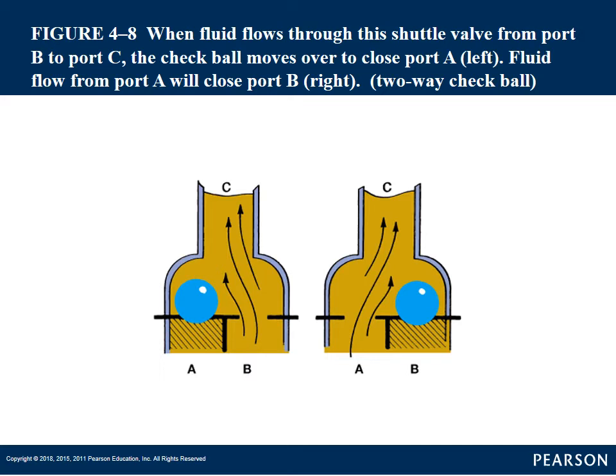When we're putting shift kits in, or if we're moving check balls, this is a check ball you almost never take out unless you make major changes to the separator plate or the valve body. Because if you would take one of these out or forget one of these, then it would apply pressure into a circuit when the transmission is not wanting pressure there. And that's almost always going to cause shift problems and or major malfunction in the transmission.